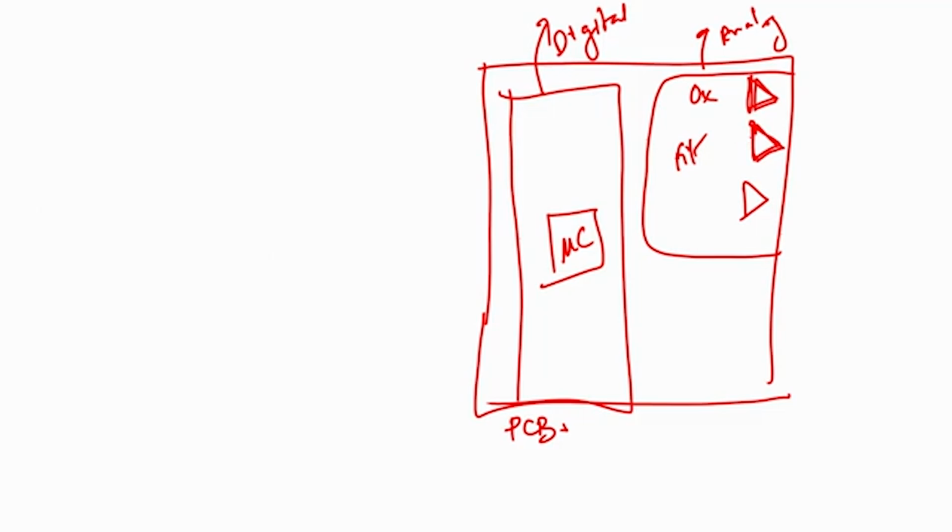This amplifier, as we have seen, will get connected to a DAC module, correct, and the DAC module will have a bit sequence, and we know that by changing this bit sequence you will be able to change the amplitude of this output, the amplification, and there comes the beauty.